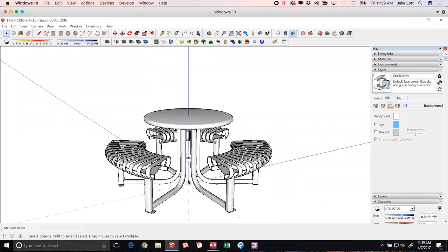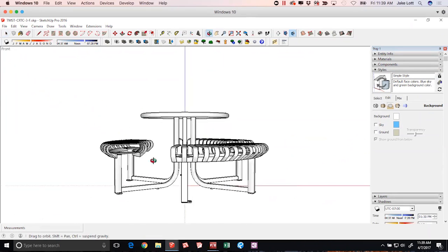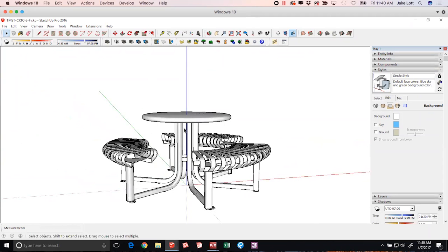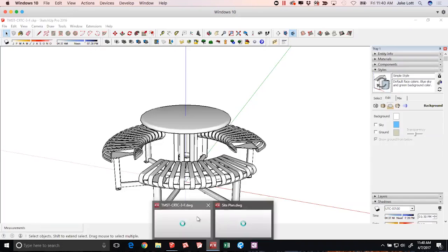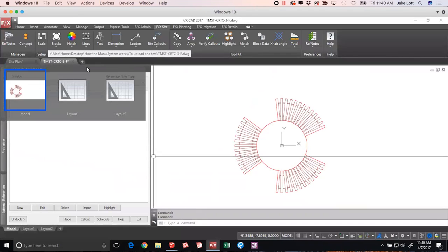And if something does end up shifted as you do your transition or your SketchUp connection, make sure that the insertion points are proper on those source blocks. And if not, we can correct it, get it uploaded, and fix it for you. That being said, there's one other real key piece of information, and that would be the naming of these things. The reason that these can be tied together is because they are named the exact same, but obviously in SketchUp format or DWG format. So having that naming structure is super important.